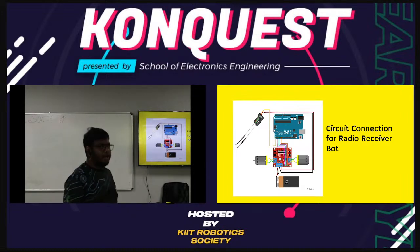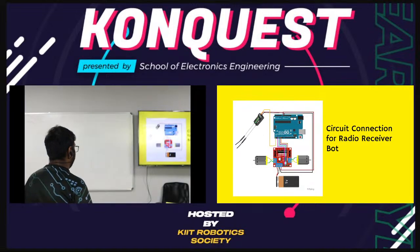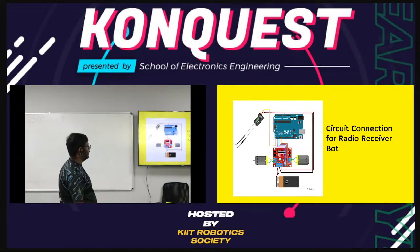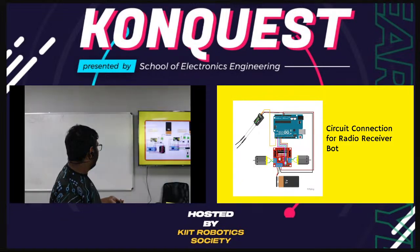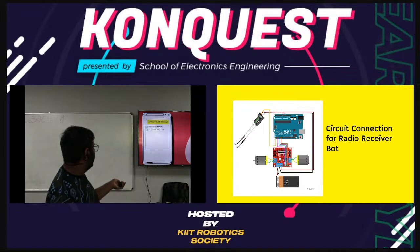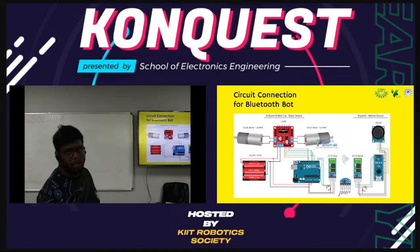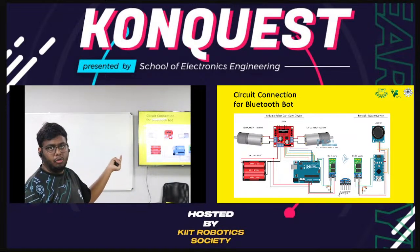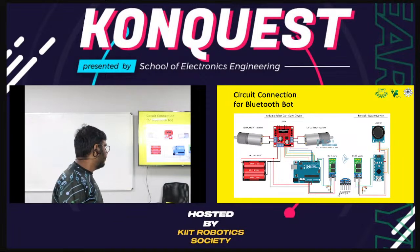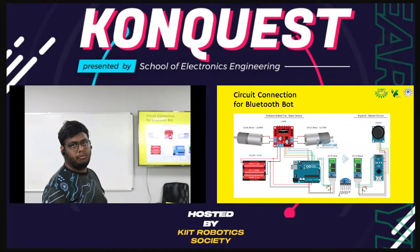This was the circuit diagram for our radio control board, for a radio receiver. Now, here there is no transmitter we have to make, unlike in the Bluetooth control board. There, we have to make our controller using a joystick and microcontrollers such as Arduino Uno, Arduino Nano, or anything else. And for the Bluetooth, we have to use another Bluetooth module, let's say HC-05.